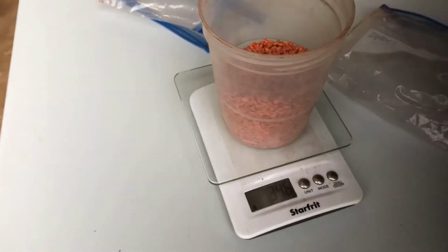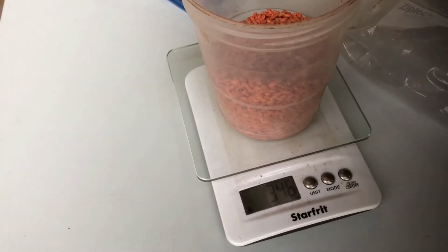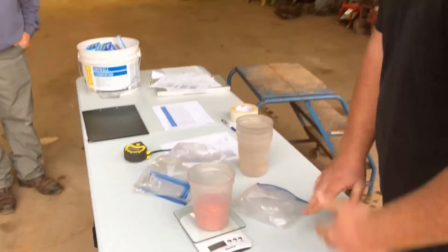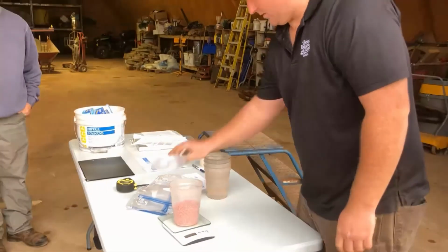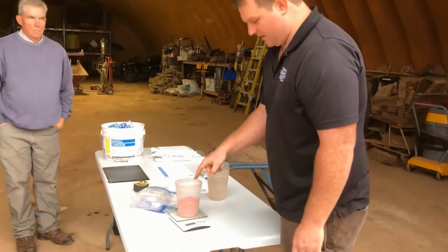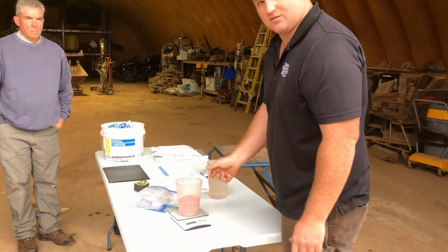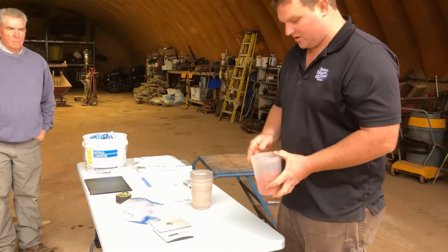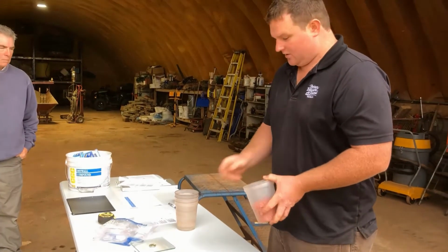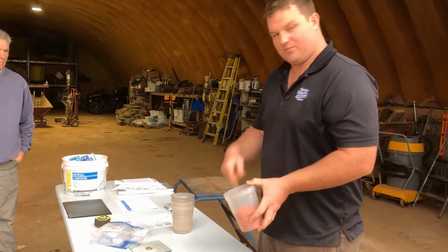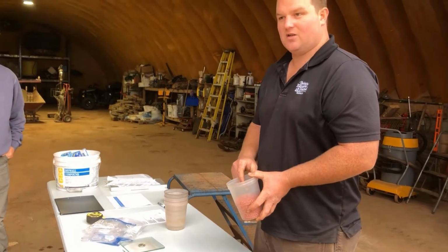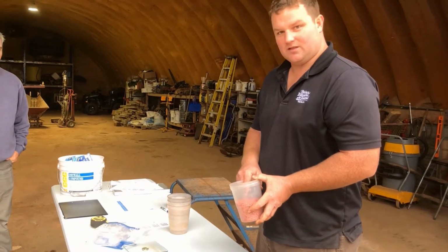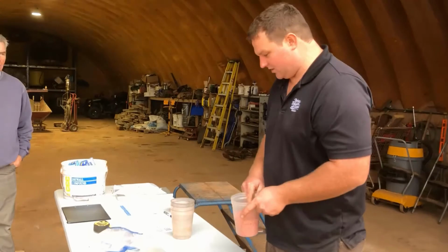So in the 4 bags, we ended up with 346 grams, and we were going for 480, so we're under our target seeding rate, but we'll do some math to figure out what seeding rate this is actually at, so we know how much we should adjust the lever before doing it again. This calibration is trial and error, so you do the math and keep repeating the steps till you get into a target of 2 to 3% is where I like to live with the seeding rate range.